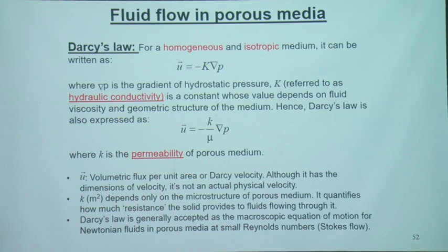So Darcy's law is generally accepted as the macroscopic equation of motion for Newtonian fluid in porous medium at low Reynolds number. This is another assumption, and in fact this assumption is generally satisfied when you look at fluid flow in the tissue. In tissues, the velocity is very low compared to the blood velocity within blood vessels.